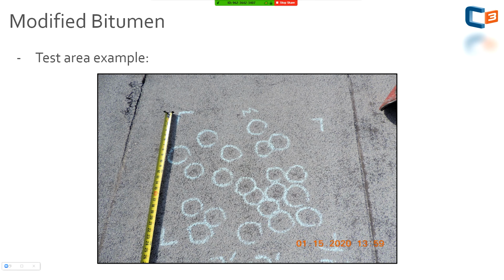So you just adjust, right? You just think, all right, what's it going to do to a coating versus just a cap sheet with granules? So we're looking at that, and then when we identify that location, we're flipping that over, separating the base and cap sheet, and identifying and documenting that fracturing. If you submit this to an insurance carrier or an engineer, they cannot ignore this.